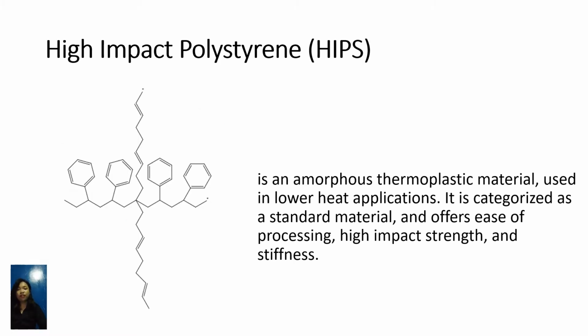So first, I'll introduce you to the properties of high-impact polystyrene or HIPS. HIPS has high tensile strength, high impact resistance, and is very light. HIPS polymer has multi-phase systems with polybutadiene disseminated in a rigid polystyrene matrix and has improved fracture resistance. It is known as strengthened polystyrene and a strong alternative to the highly brittle and rigid polystyrene.